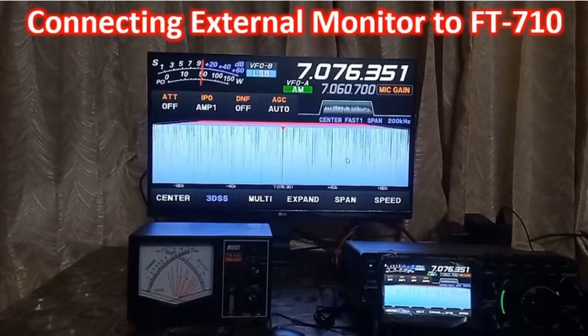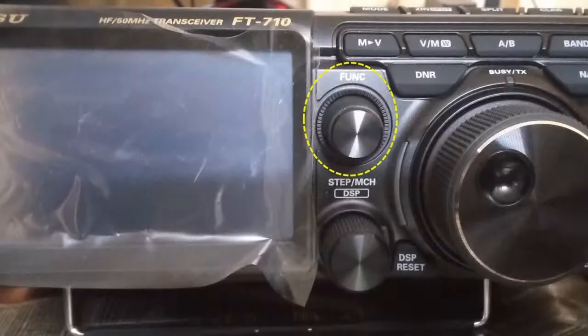So a DVI-D monitor and cable were bought online. But simply connecting it to the DVI port and giving power did not work. The function key of the radio had to be accessed to get the display settings and enable the external monitor. Pressing the function key brings the options on the TFT monitor, from which you can choose the option from the touchscreen function. As I had already connected a mouse to the Type A USB port at the back of the radio, I used the mouse for accessing on-screen functions.